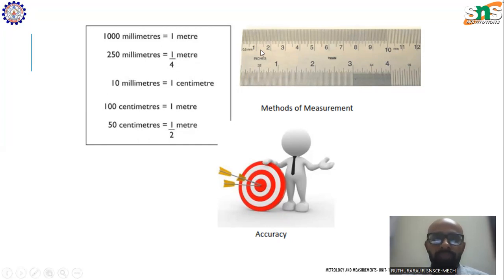But if you see closely, from 0 to 10 mm, there are numerous divisions. Each small line represents a millimeter. But here there is another smaller line between those two indications. That is 0.5 millimeter. That is not a widely accepted form of measurement, but it can be utilized for measuring 0.5 mm also. But generally, in a scale, the least possible measurement is 1 millimeter.